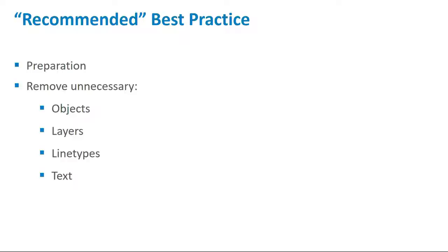There are ways of going to Excel, and there's a couple of apps out there that will do a link from Excel into a schedule. But generally you have to start with the schedule first and do the export, add the data that you want in the Excel and then bring it back in. But then that stays as a live link. But tables, unfortunately not.